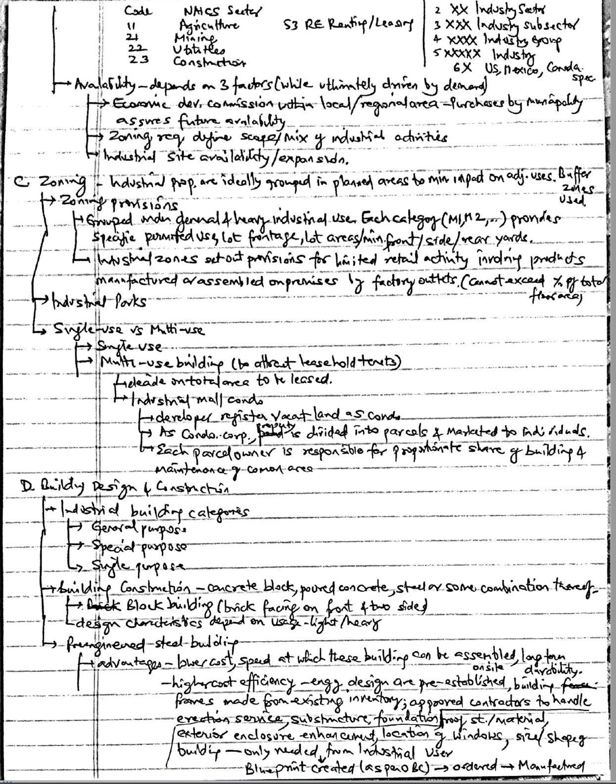Building codes set out live load requirements according to the use and occupancy, that are normally expressed in terms of pounds per square foot or metric equivalent for the various types of uses. The minimum specifications are typically stated as a uniform distributed live load on a floor area in relation to the particular use. The building code will set out differing minimum specifications